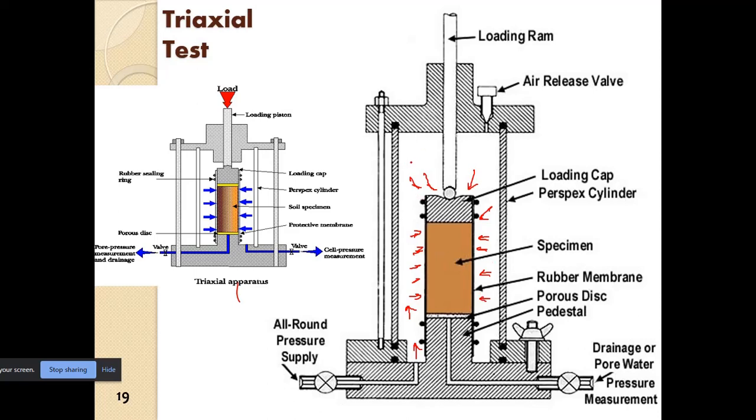In fact, as we know, cell pressure, water pressure, will act in all directions, so on the walls of the triaxial cell also it will apply. So in the entire liquid that is filling the cell, whatever pressure we are applying, suppose we are applying 100 kPa here, this 100 kPa will be transmitted all throughout the cell. That is the confining stress.